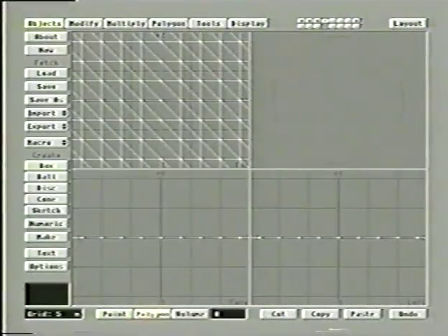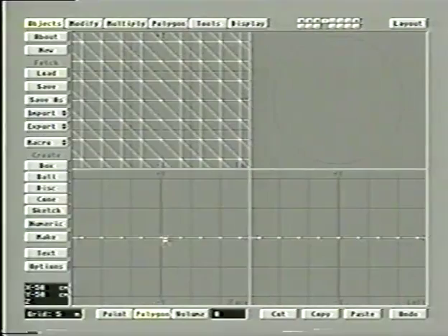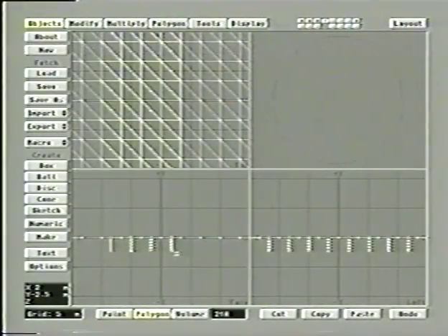So we've done that. Let me also mention one other thing about drawing out a flat piece of landscape like this. Remember from tape 1 we talked about the fact that polygons have a facing. They face one way or another. Well, anytime in this version of Modeler, 3.0 or 4000, you drag out a flat polygon, it's going to face downward, which is not the way we want our terrain facing, obviously. You can see that if I choose polygon and select a couple, notice they're facing down. So we don't want that.